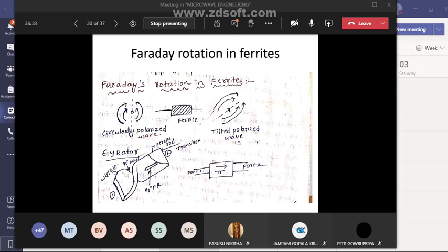So here from port 1 to port 2 we have 180 degrees phase shift, and from port 2 to port 1 we don't have any phase shift, right? So it consists of circular waveguide and rectangular waveguide at both ends of the circular waveguide. And inside the circular waveguide, the ferrite rod is placed. Okay. If you see the working of this gyrator, when a wave enters at port 1, it is port 1 and it is port 2.